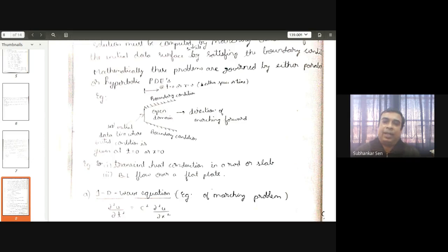So we know the solution now. Using this solution, we can calculate what the temperature will be after 5 seconds. Using that solution, again we can find out the temperature after the next 5 seconds. Like that, we can calculate the temperature after 1 hour. It means that knowing the initial solution, we are predicting the temperature in the future. So we are moving in time from present to future. This moving is known as marching. Okay, so this is marching forward.